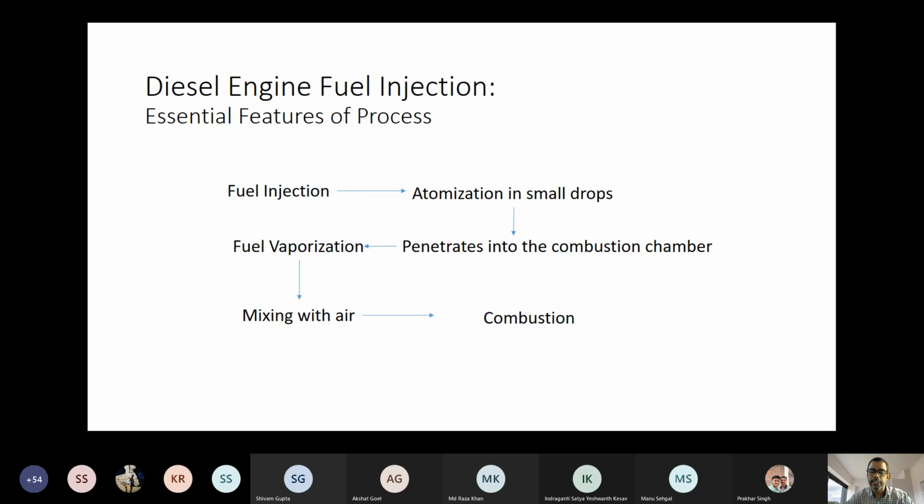The stoichiometric air-fuel ratio is very close to 14.6 or 14.7, so 18 or 20 is where we come closer to stoichiometric conditions. Otherwise, in the lean mode, where the engine is idling or at slightly low speed and low load, it varies around 60 to 70. So there is a wide range of variation of the air-fuel ratio in the diesel engine.